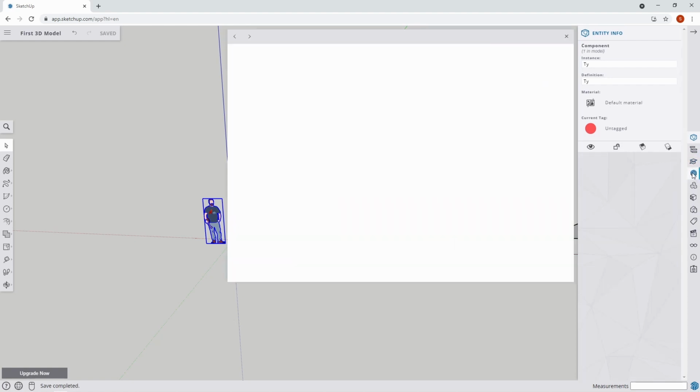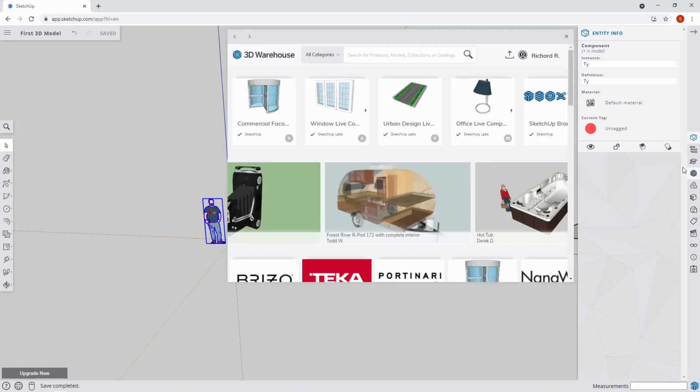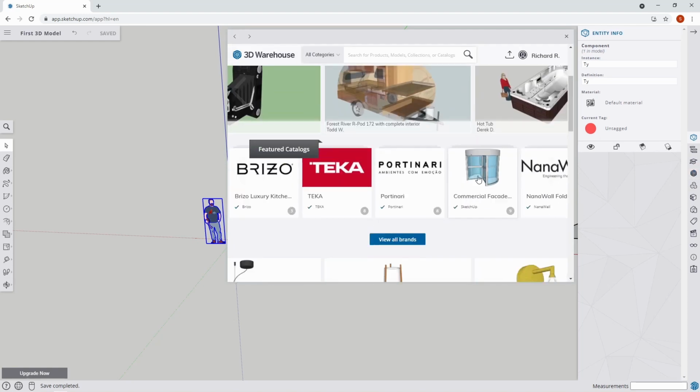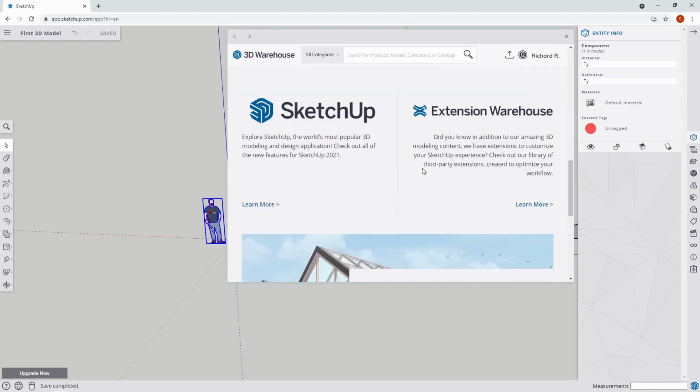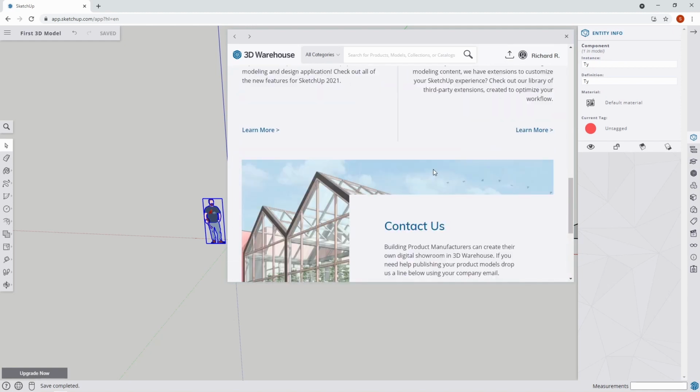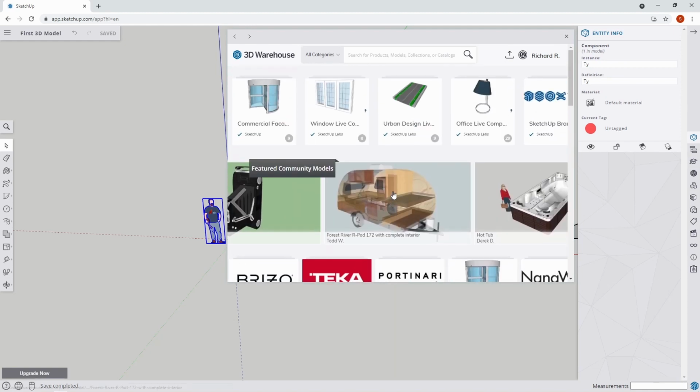The next one is the 3D Warehouse. This is kind of neat because it allows us to see some of the other objects people have created and to import them into your own 3D model. My only caveat is that if you bring in some of these objects, they can make your SketchUp run really slow, because the more polygons your computer has to render, the more powerful your computer has to be. So in case you import something and you notice it gets really slow, it's probably because someone designed it on a really powerful computer, and when you bring it in, it's hard for your computer to render.